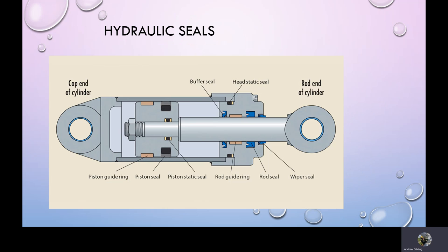Seals. We covered seals and all different types of seals and what they do. And for instance, here is an example of a cylinder, a linear actuator, and there's various different seals on there. We have the guide ring, which keeps that cap centered inside the piston and prevents the wall from becoming scratched. It's usually made out of PTFE or a Teflon, and our piston seal itself is probably some kind of an O-ring or a butyl rubber. There's a static seal there on the piston itself where it connects to the rod to prevent fluid from going up the middle there. And on the annular side, we have, again, another rod guide to make sure that rod goes in and out smoothly, and that may be made out of brass or a Teflon again.